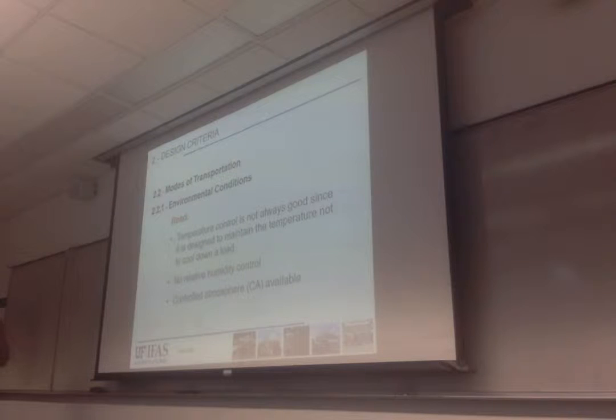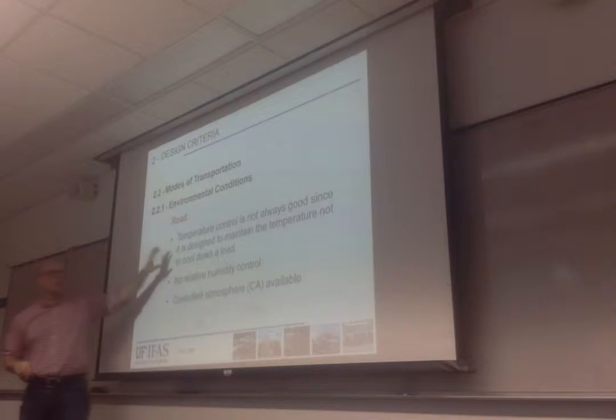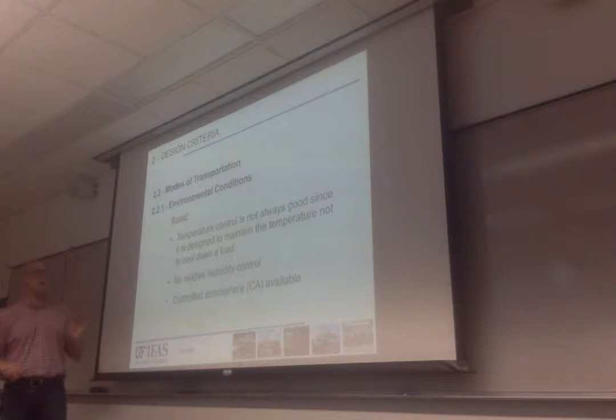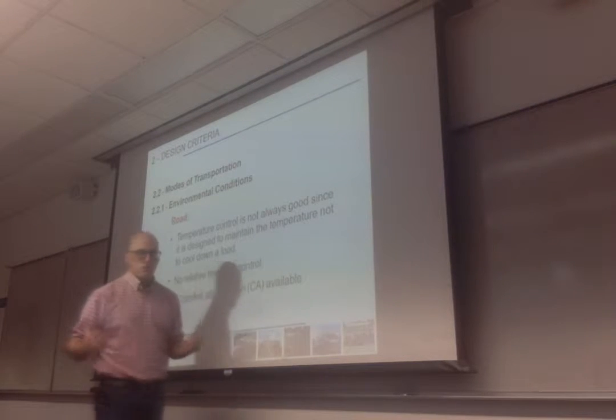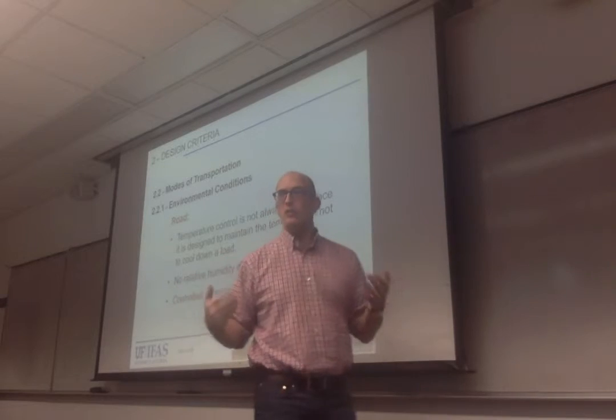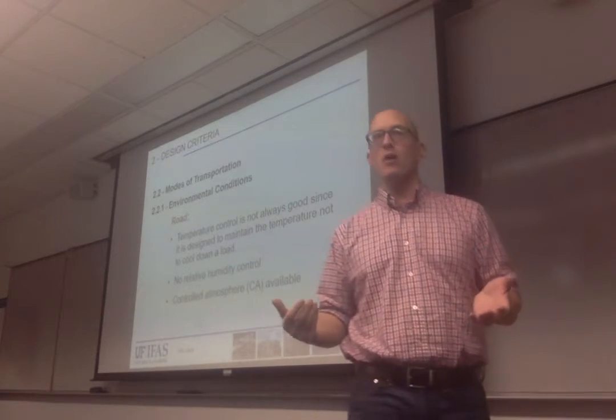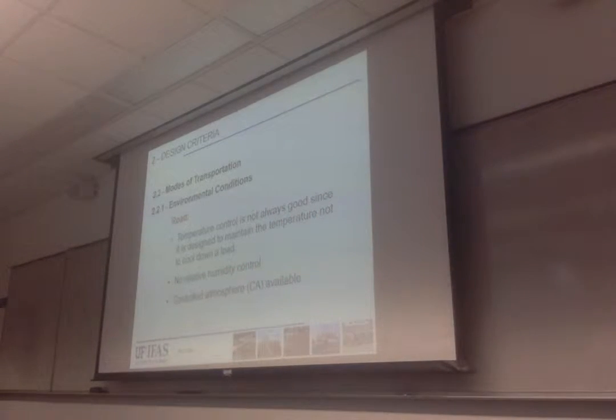But one thing that is major is that road transportation temperature control trailers are designed to maintain the temperature of a load. They are not designed, they don't have the capacity, to cool down an entire load. That's very important. So if you have a temperature sensitive product and you load it warm into a trailer, it's not going to work. It's not going to perform well because it's designed to maintain the temperature.